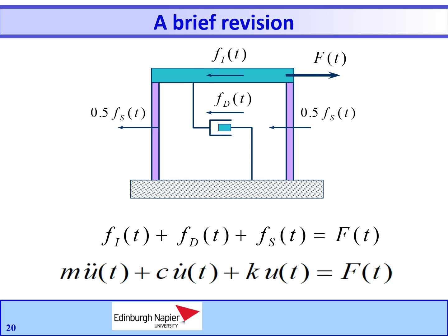We are now at a point where we have formulated the governing equation for the idealized one-story frame based on the action of the external force F, and we are now describing the state of the system by introducing terms linked to the displacement u, the velocity, which is the first derivative of the displacement, and the acceleration, that is the second derivative of the displacement. Now you can visualize the system as a combination of three pure components: the stiffness component, the damping component, and the mass component.